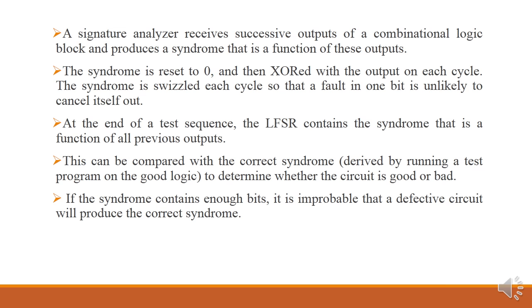The pseudo random sequence generator is used for giving the input signals, and to analyze the output we use the signature analyzer. The signature analyzer receives the successive outputs of the combination logic block and produces a syndrome that is a function of these outputs.